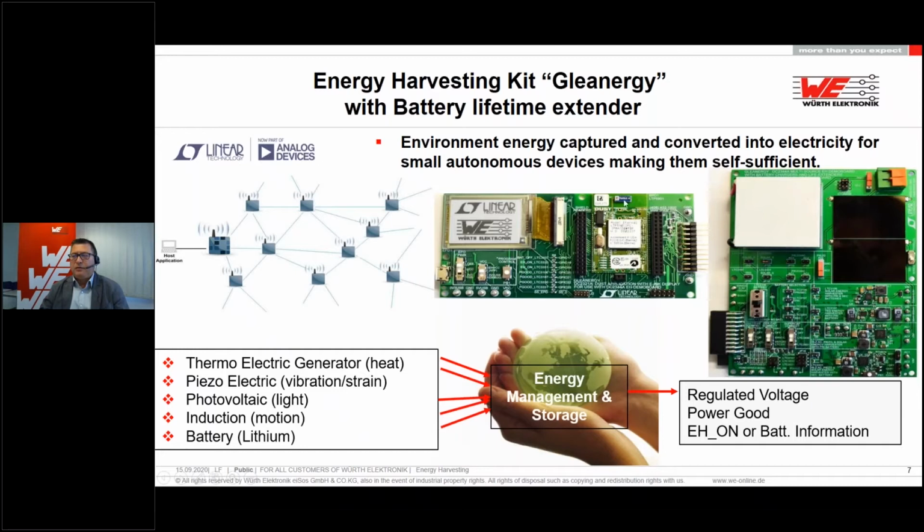You can even measure the current consumption. Behind this board there is also a coulomb counter, because measuring 150 nanoamps is not trivial. It's very difficult, and you need to power this coulomb counter, which sucks much more energy than the power board can provide. For this reason, you have a USB port here.